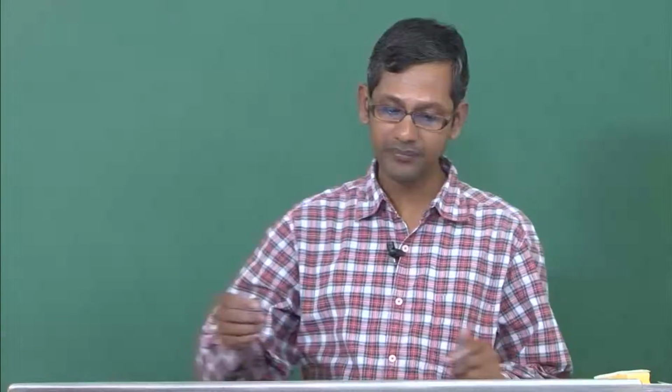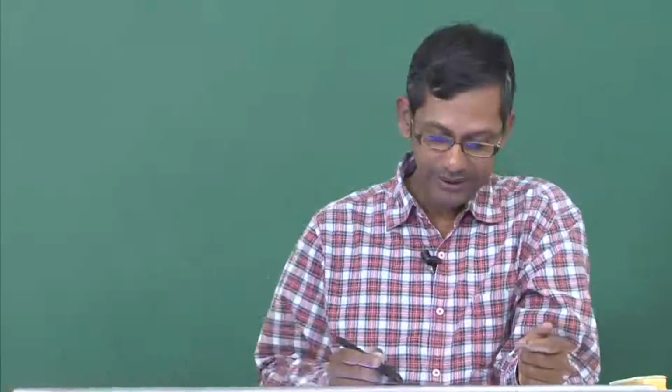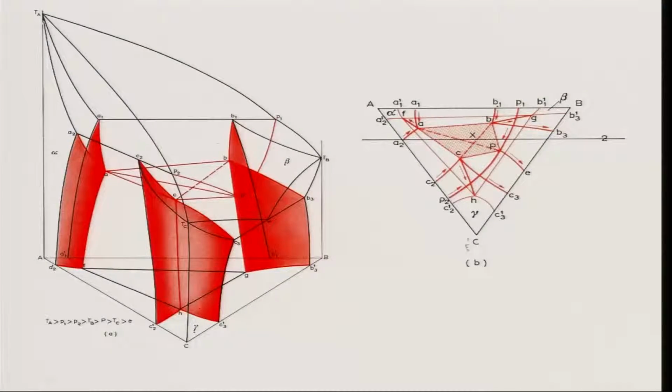Okay, actually same things here, so you can understand in a better way. So, see, if you look at that A, B, C, right, A and B, A forms peritectic, and this peritectic is represented by P1, and AC forms a peritectic that is represented by P2. You can clearly see this is a peritectic.